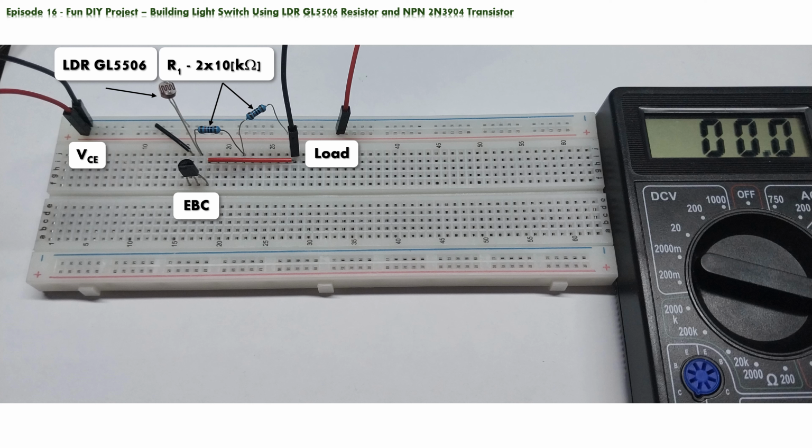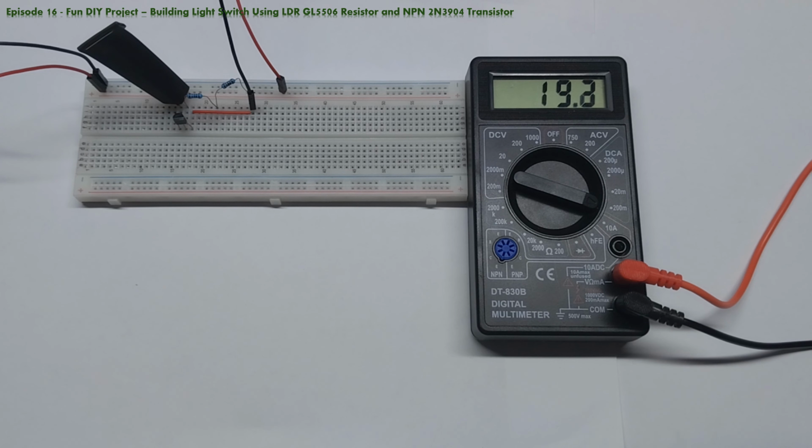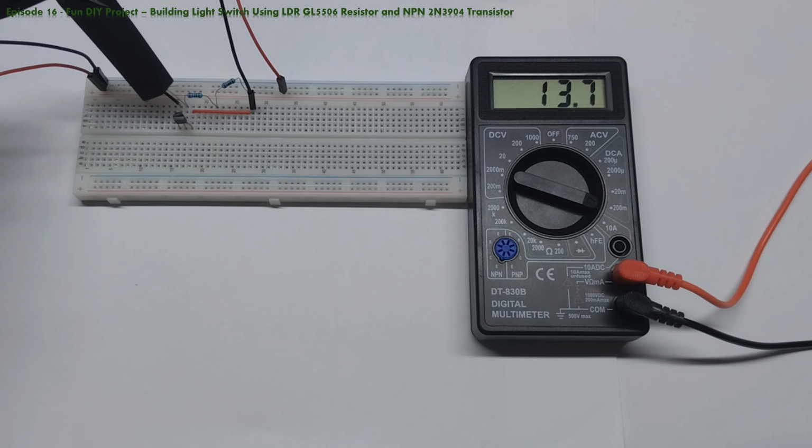Everything is powered up, so our multimeter displays 0 amperes of collector current, as it should be. As it would be impossible to record video in the dark, we made a small black cap to cover the LDR to simulate dark conditions. As you can see, when the cap is on, the LDR goes into dark, and the collector current jumps to approximately 20 milliamperes, which is well within the tolerance, and our circuit is on. When the cap is removed, the LDR is lit, and the collector current goes back to 0, so our circuit is off. So, the conclusion is that our circuit works as designed.